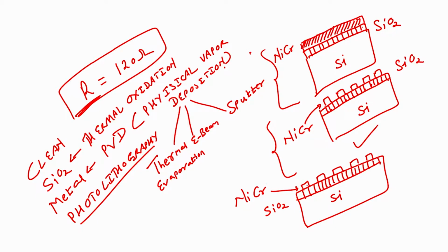On this micro heater, what I want is interdigitated electrodes, but if I directly deposit metal on this, is it correct? No, because the heater is also made up of metal, and my interdigitated electrodes will also be fabricated using metal, chrome gold. So, what should I do? I cannot put one metal on a second metal, otherwise it will be shorted.